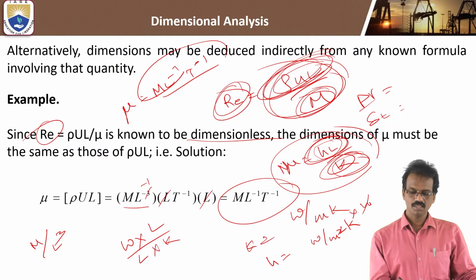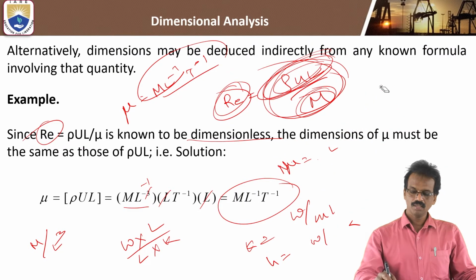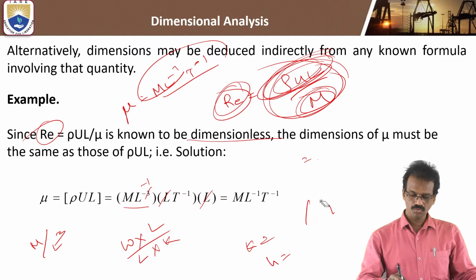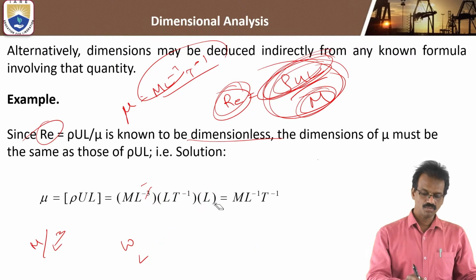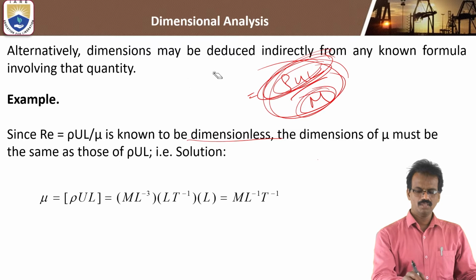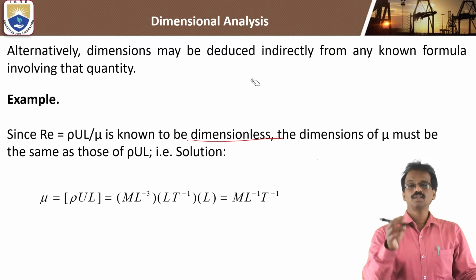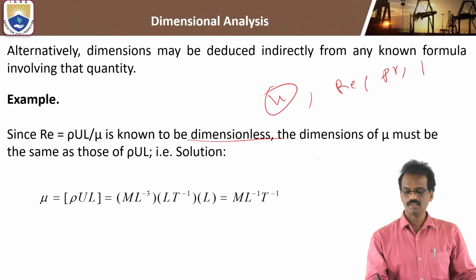So this is the Nusselt value. In this way, just like we can convert all the physical quantities into some groups. By using those dimensionless groups, we can study the rate of heat transfer process, and we can find out the heat transfer coefficient with the help of Reynolds number, Prandtl number, and Nusselt number.